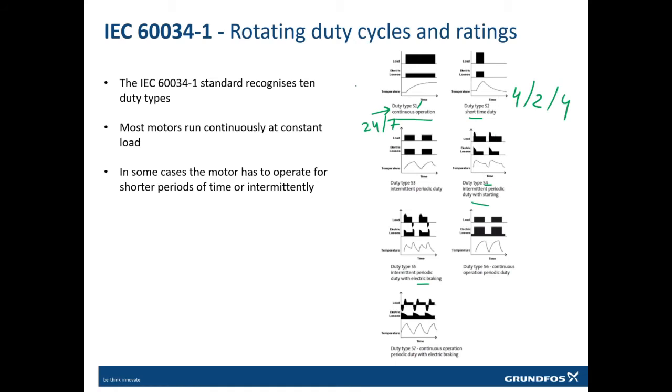But for pumps, the motors used are always S1 duty, and it should be S1 duty, because these motors are designed to work 24 hours a day and 7 days a week. There is no stopping or mandatory stopping required for the motor of the pump.